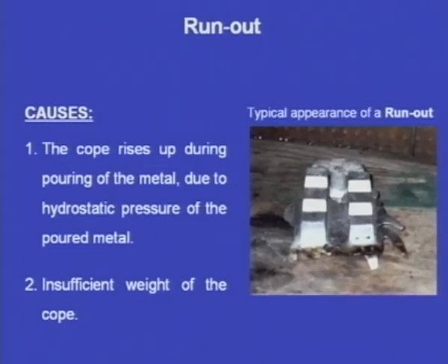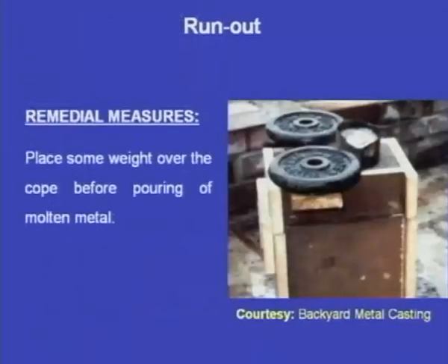And another reason is the weight of the cope is not sufficient. That is why during pouring the liquid metal could lift the cope up and the molten metal could go outside along the parting line. And what are the remedial measures to be taken?